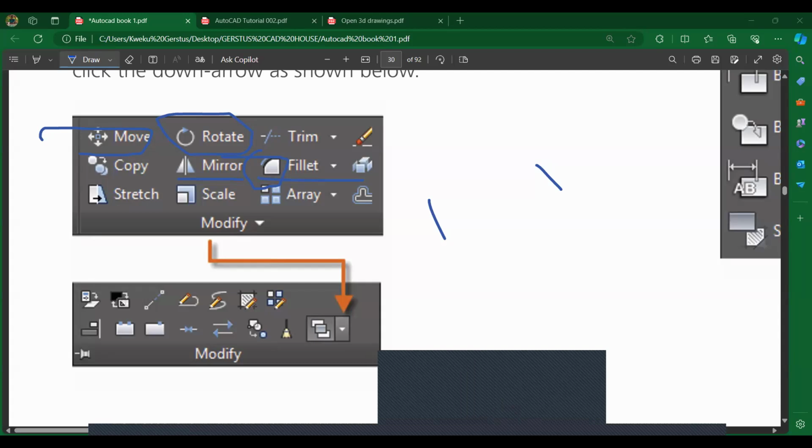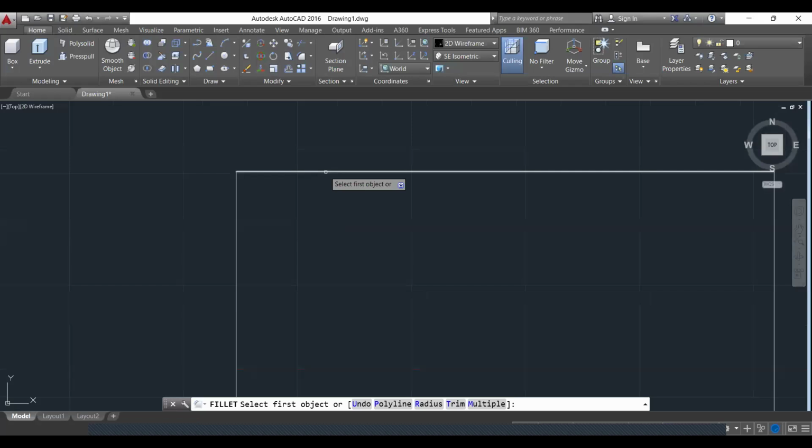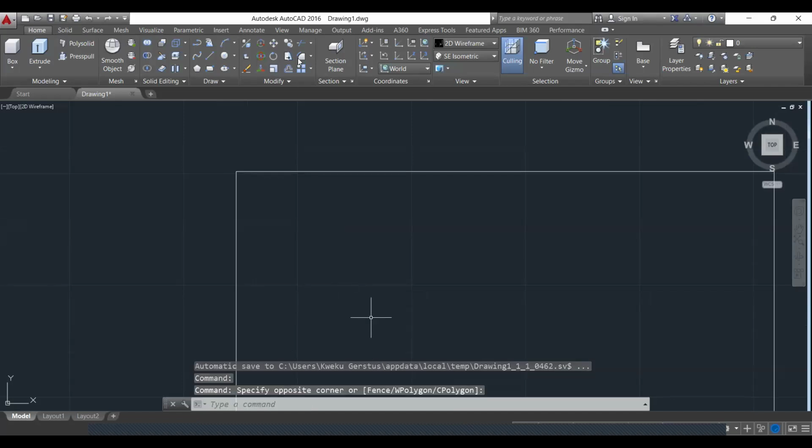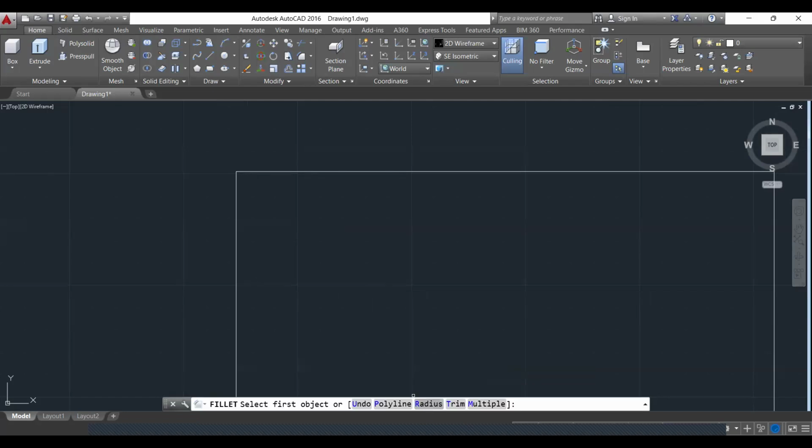All right. So when you have something and you want to fillet, assume I want to fillet this edge, right? I'll select the other line and select the other line and give the radius. You can select your fillet. You come down here to the command button, give the radius at which you want to fillet. Assuming I want to fillet it 100, I type in my 100, press enter,